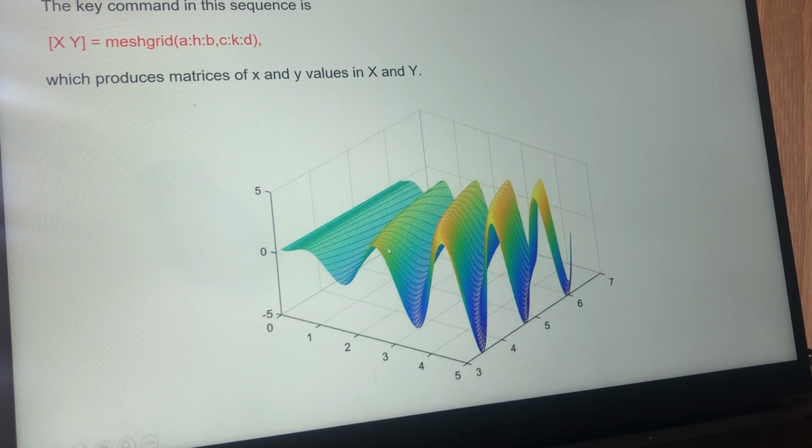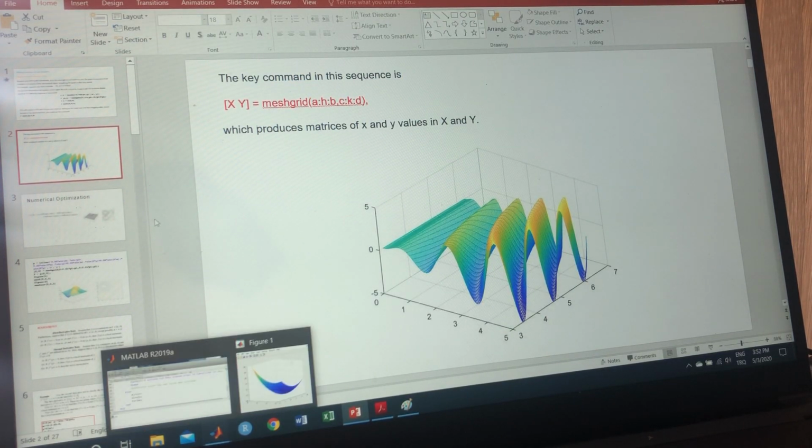And in MATLAB, you can even rotate this, and you can check the graph from different points, okay, from different angles. And in this part, the mesh grid command is important. So in mesh grid, the first output has the information of x, and the other one has the information of the y value. And you are plotting this x and y space onto the z function, and you are plotting that like that. And I can show this one in MATLAB to you.